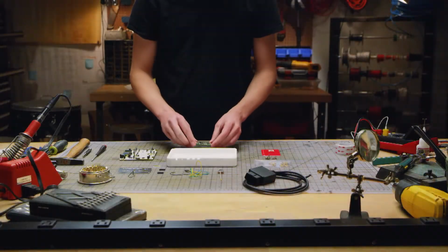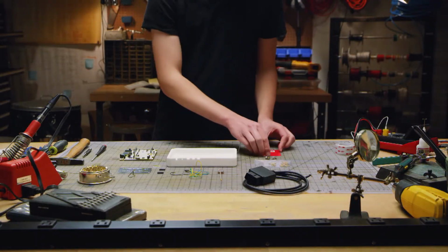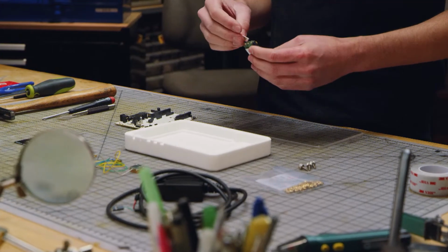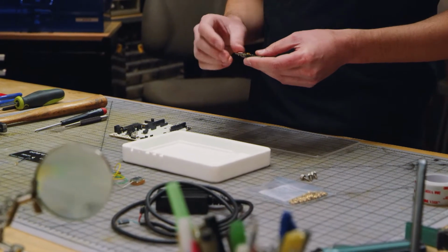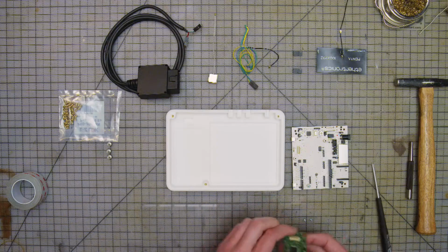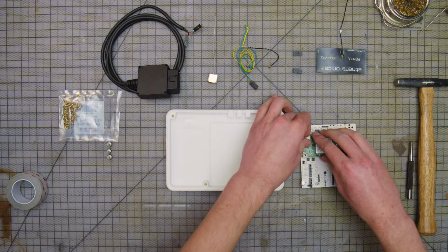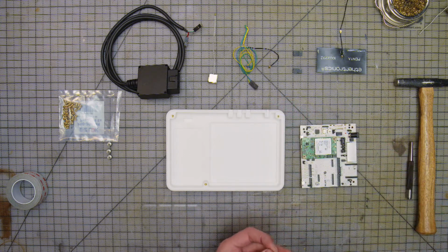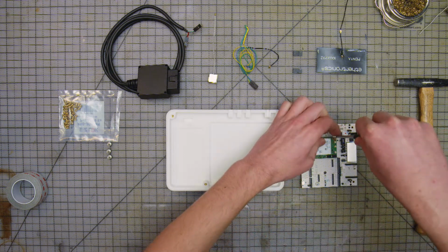Next, we will prepare the ST Dragonfly microcontroller, which contains all the computational hardware for this device. This involves inserting the Twilio SIM card, then placing the microcontroller into the appropriate receptacle on the multi-tech breakout board. Flash the microcontroller by connecting to USB ports on the breakout board and the microcontroller itself.